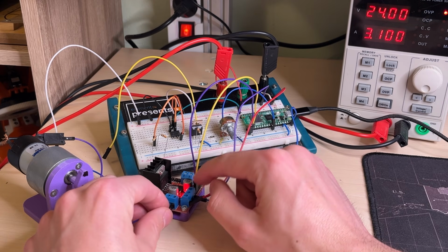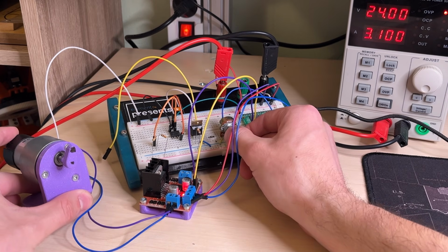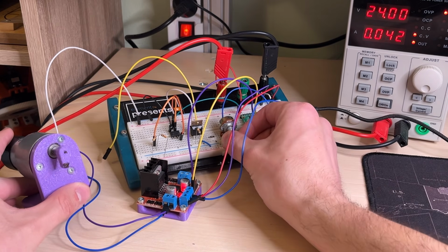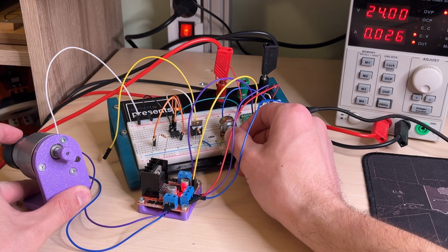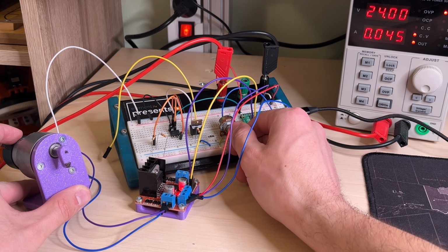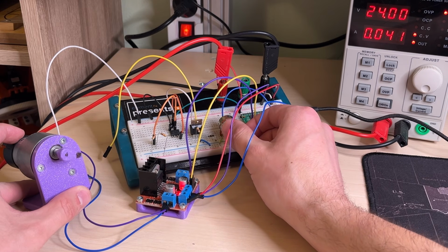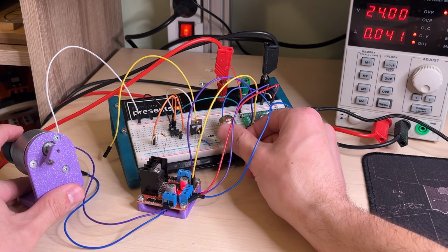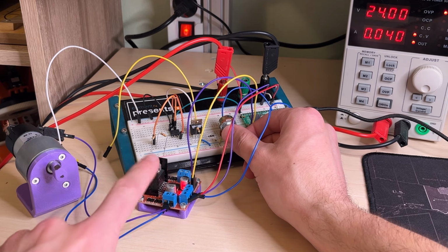So we either drive one of them and the other one should be pulled to ground. If we do that, if we turn the potentiometer to one side and turn on the power supply, we can spin the motor in one direction. And if we keep turning the potentiometer to the other side, it first slows down and then it starts spinning in the other direction. So essentially with this we get full control of the motor. So for our motor driver, the one that we will be building now, we want some kind of an H-bridge, and since I want to control 2 motors, we will need a dual H-bridge motor driver, something similar to this.